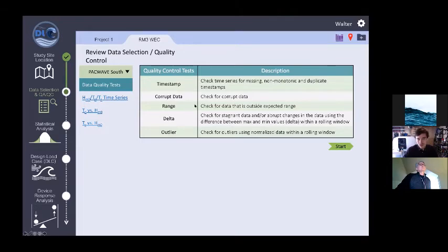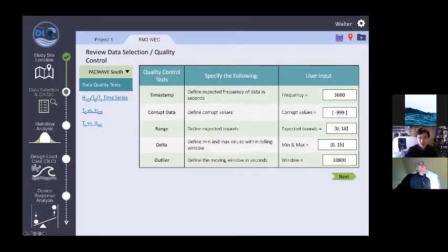We're going to just look for missing, corrupt data, things where you've got a wave height of 100 meters. That's probably a little bit fishy. And you can set what those would be. So, okay, we know that the SWAN data set, for instance, uses 999 to designate missing values. And if we're talking about wave period, anything above 18 seconds is maybe a little bit fishy in terms of peak period.